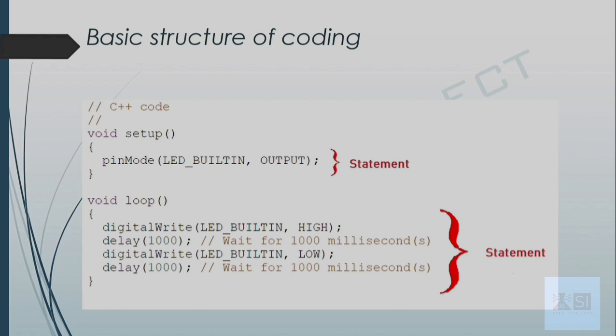The most important thing is that we always have to write this function even if we are not writing any statement in it. Which function? Void setup, the setup function especially. The loop function is called the execution function. The code written in this function repeats forever until we stop it. Whatever we are expecting from our project, we are going to write that code in between this one.